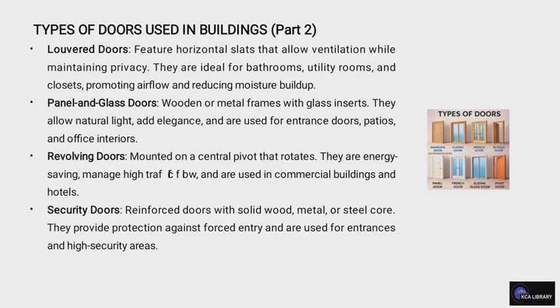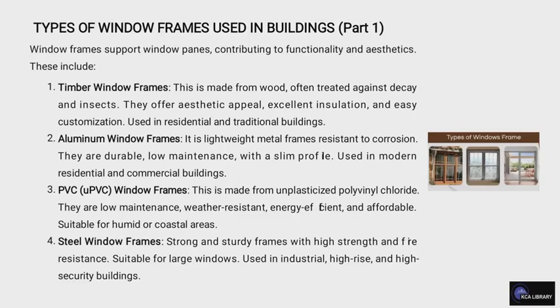And we also have the revolving door, which is mounted on a central pivot that rotates, and they are energy saving, manage high traffic flow, and also are used in commercial building and hotels. We also have the security door, which is a reinforced door with solid wood, metal, or steel core, and they provide protection against forced entry and are used for entrance and high security area.